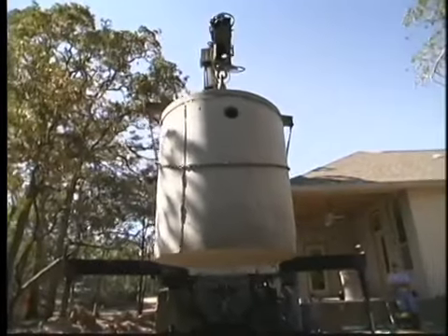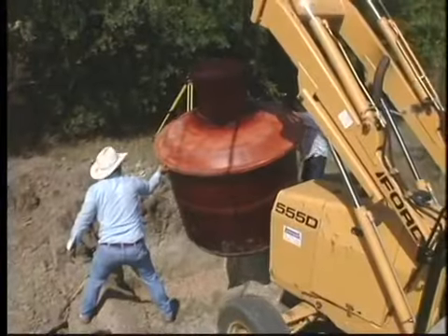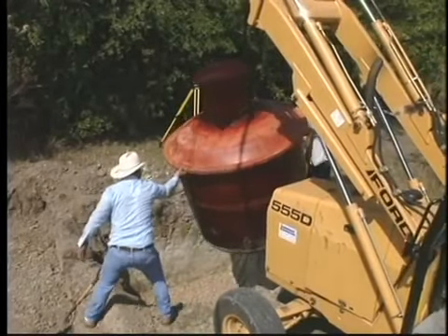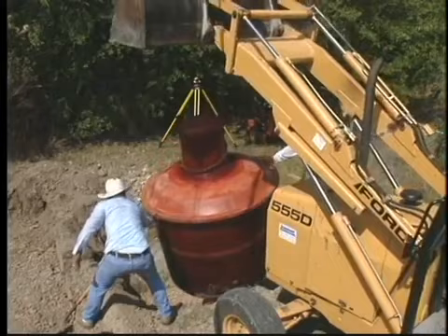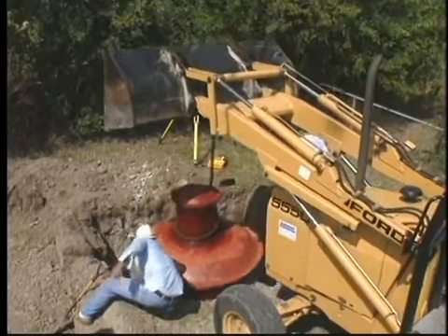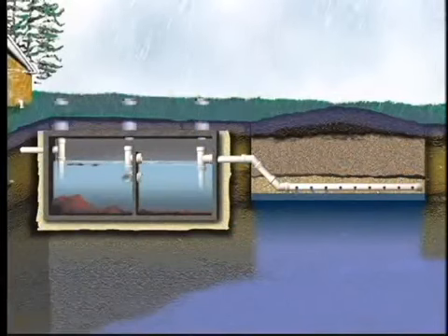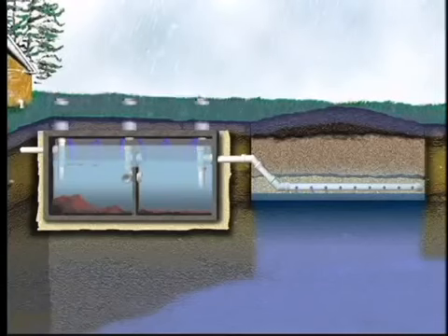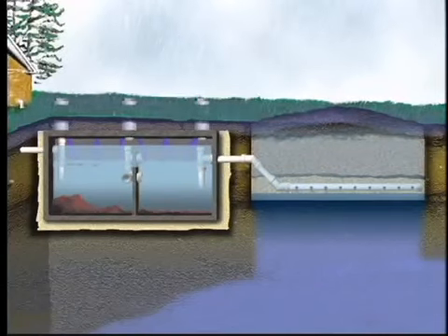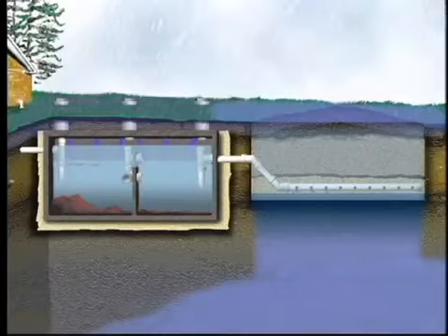Most of the septic tanks are made of concrete. However, fiberglass and plastic polyethylene tanks are becoming more prevalent. These are lightweight and ideal for hard-to-reach spots. All tanks must be watertight to keep water from entering the system, because excess water entering the system can saturate the soil absorption field. The result is water flowing above the ground surface.